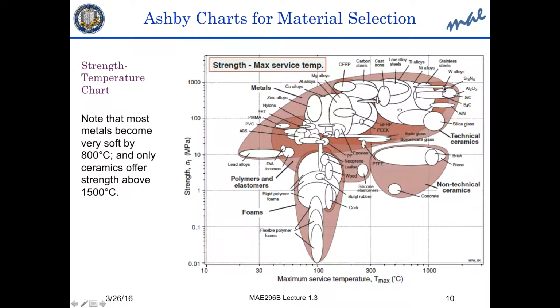Or I can consider alloys, and the alloys are a little bit off, like the tungsten is in between, it has high strength and a high temperature. But then as you go to steels, you get lower temperature capability, nickel alloys, titanium alloys, and so forth, like we explained before. So you're moving backwards in terms of the temperature range.